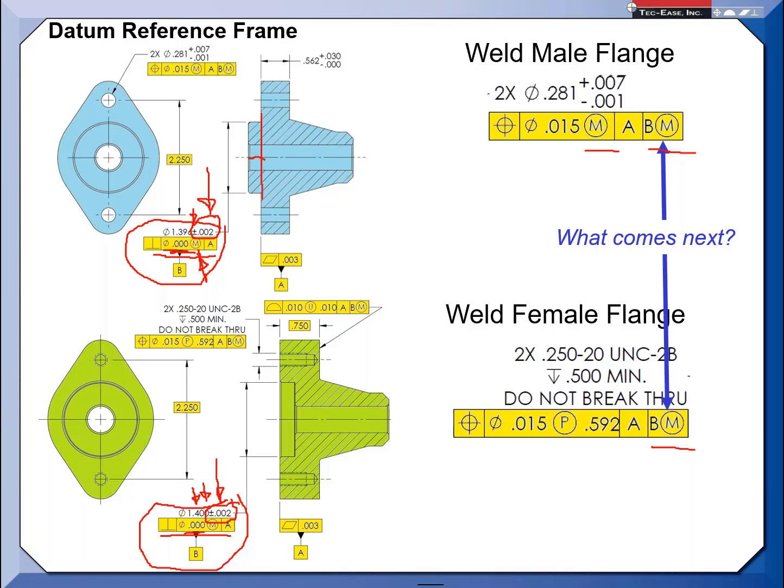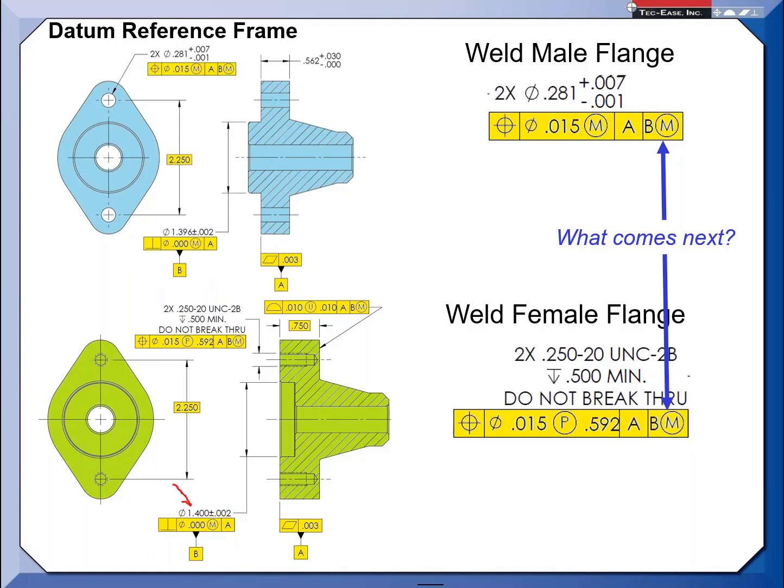I would hope my fabricators are focusing on a nominal number like this. If they center on this value, what are the odds of both going to their MMC size and then coming together? That's the risk I'm dealing with. Did that help? Yes, it did.